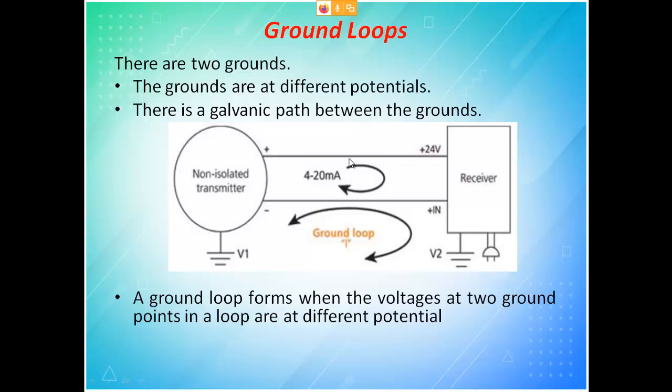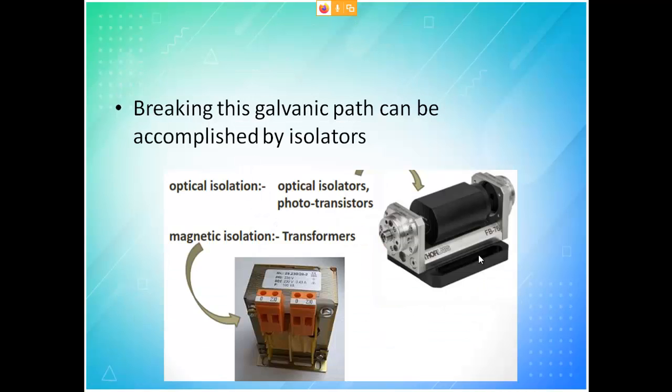To avoid this circulation, go for twisted wire cable. Don't use separate wire cables. When you go for twisted, this end becomes this end and this end becomes this end, and since it is twisted, this will get entirely zero. The ground problem can be solved by totally isolating. That is what we do with isolation grounds.